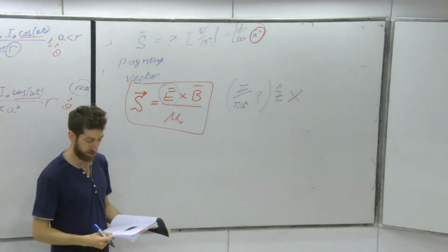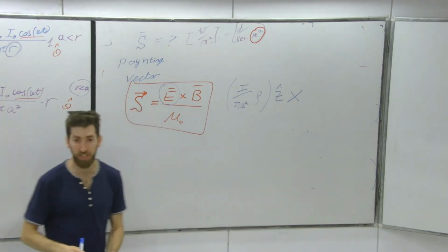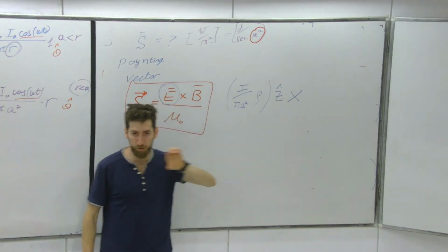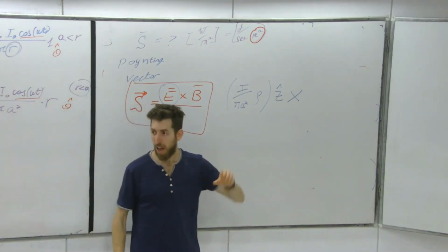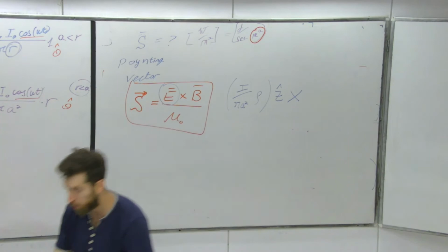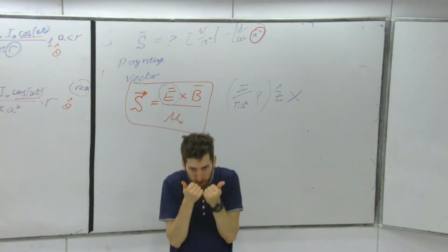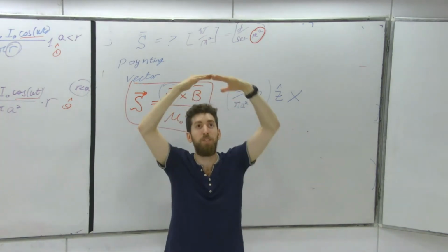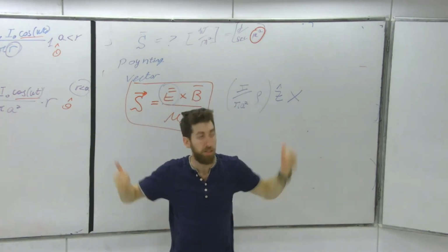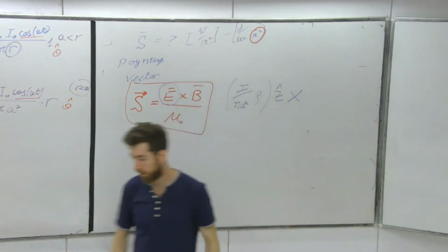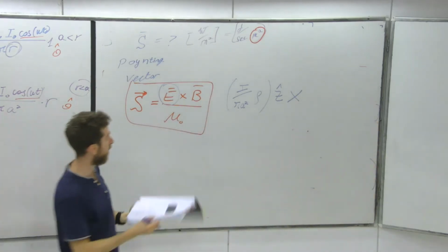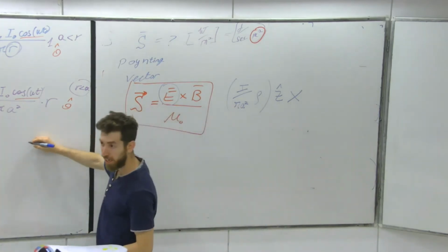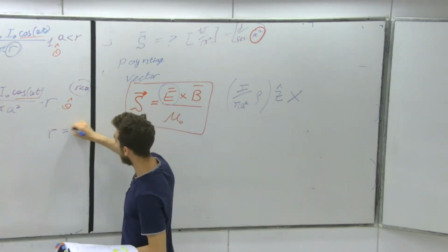We just found B. And I want to take care of the dissipation of energy through the surface area of the wire to the environment. I don't care about this radius dissipating energy to that radius. No, I want to know the outer shell of the wire dissipating to the air, okay? So this is the magnetic field in the special case of r equal a.